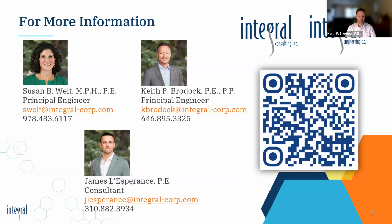Sure. I'll throw a couple ideas out. One of the things that we're seeing with climate change is sea level rise. Especially as we are installing a vapor intrusion mitigation system, whether it's an SSD or a vapor barrier, for instance, when we're near the coast or near bodies of water, with sea level rise, groundwater also rises. And whether that's more saltwater intrusion coming back inland, or generally everything is rising all at once,